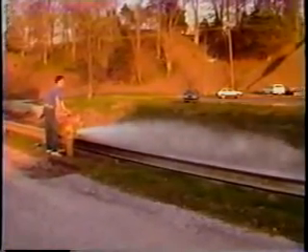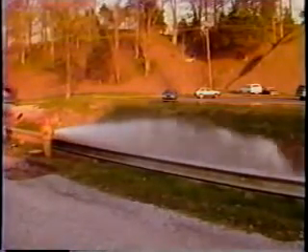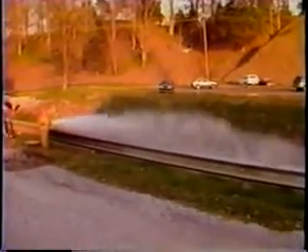Now that we've defined residual hydrant and float hydrant, it's time to define some of the quantities that we're going to measure during the test. The first quantity is the static pressure, P sub S. This corresponds to the pressure at the residual hydrant when the hydrants are not flowing. So this is the pressure during normal water use at the residual hydrant.